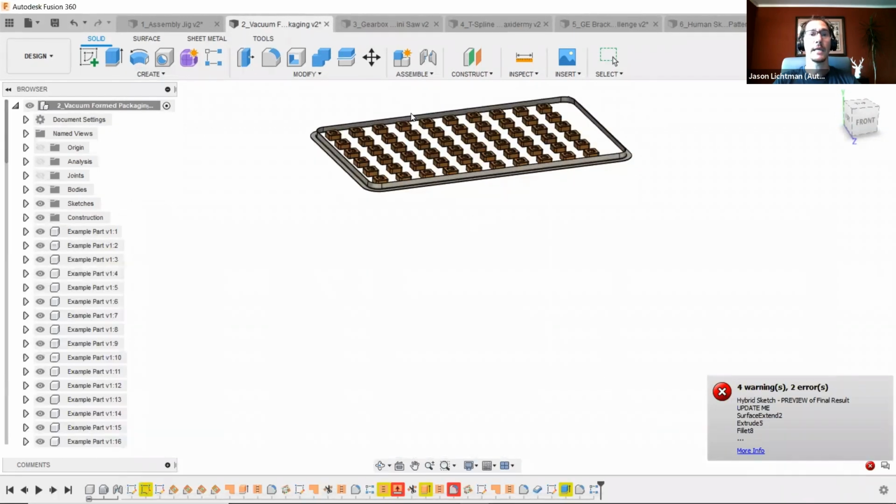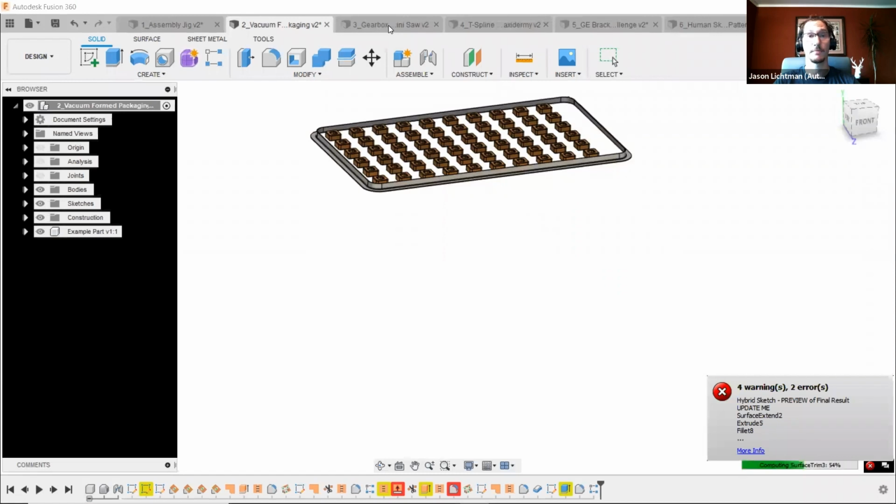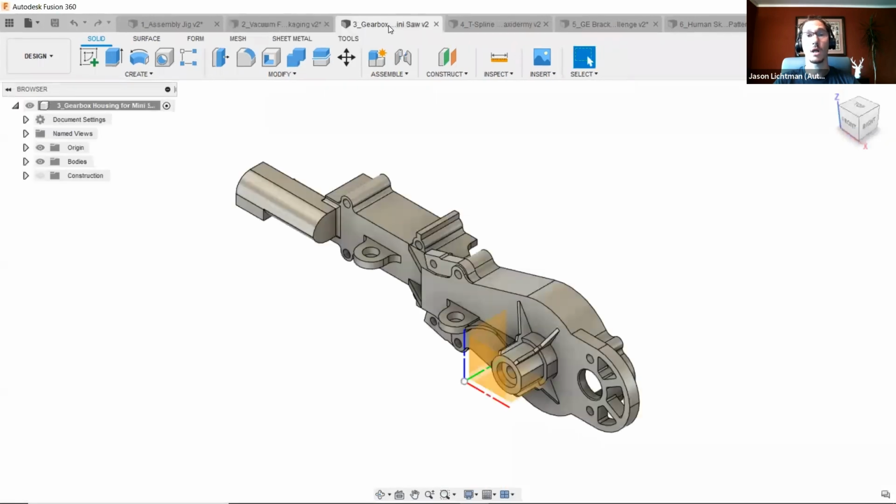Absolutely. But if you want one place to be able to change everything, you could do that here under this parameters table. Now, the next technique that I want to show you for designing, I think is really handy. It's called direct editing, sometimes called direct modeling. And direct editing and direct modeling, it's all about being able to take a design and be able to edit it directly. The most common example for that is going to be bringing in what we call a dumb CAD file, meaning a CAD file that comes from some other software and you don't have the history for how that model was created. So you don't have that parametric sketch or parametric feature to go and edit, and yet you have to make some pretty serious changes to it. Direct editing or direct modeling is the best way to do it.